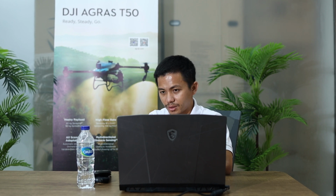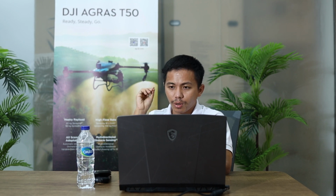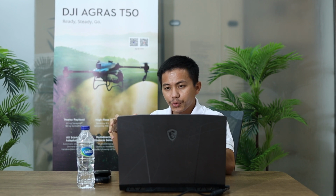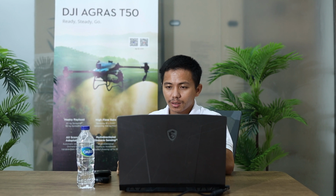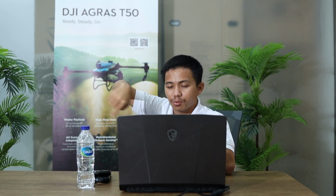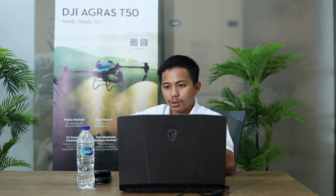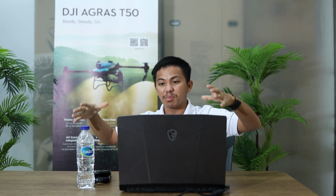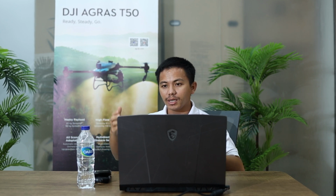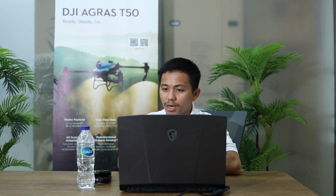This is for continuous. For spot spray, the drone will go, stop and spray. For small trees, the affected radius is 6 meters, so it is a 6 meter diameter. The drone stops every 3 meters. If your tree canopy is big, more than 6 meters in diameter, you may need to select one spot, maybe 2 spots or 3 spots. That's how you can optimize by yourself.